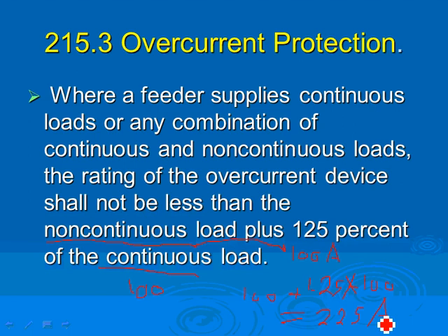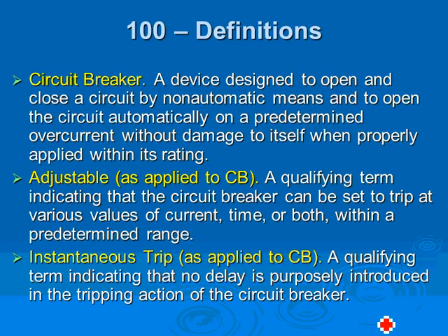Any comments, guys? Any questions? So that's 225 amps you can pull out of this, the size of your panel. If that is the size of an overcurrent protection device, what if I end up with 230? What do you do? What's the next standard? From 230 to 250. You go to the next standard. Okay, overcurrent protection devices, guys, some of them are circuit breakers.